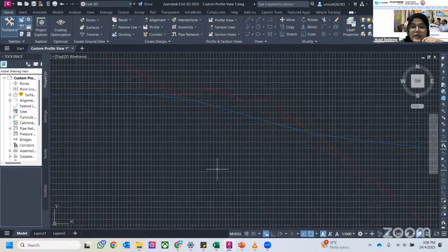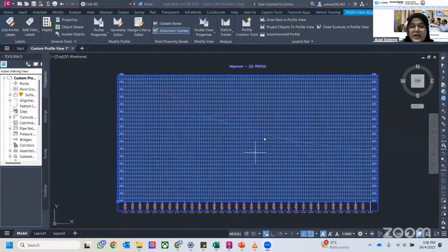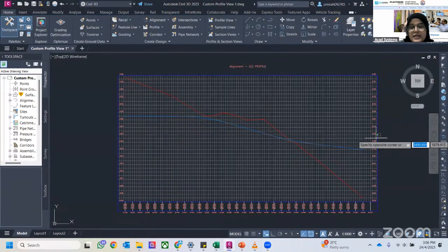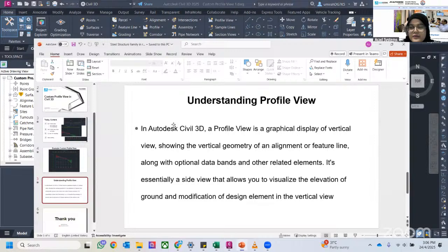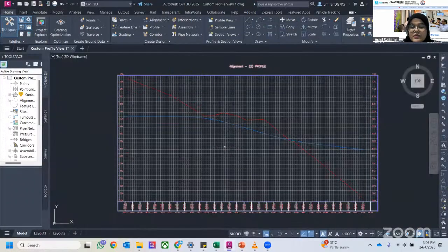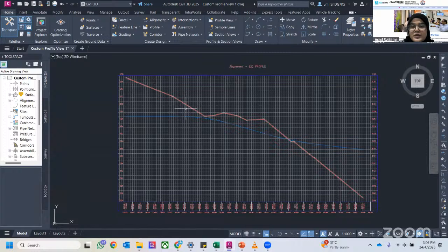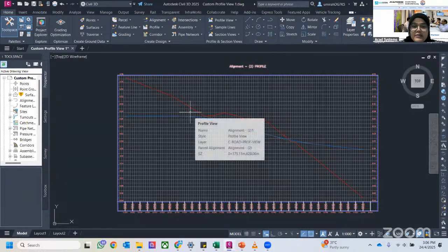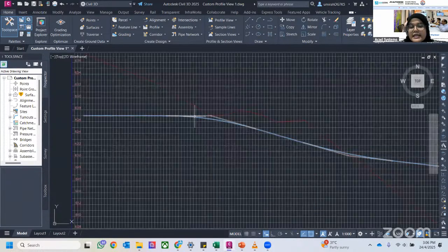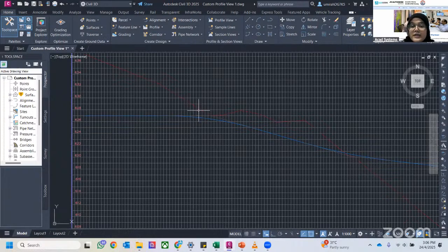Okay. So I already opened my Civil 3D here, and I already created the basic profile view like this. I'm using the existing profile view style, right? So now I'm going to change this profile view to this example. So the first thing I'm going to do is change the profile style. So what is the difference between profile view style and profile style? The profile style is the line style. Okay, the line, the color, the markers, and so on. So that is the profile style.